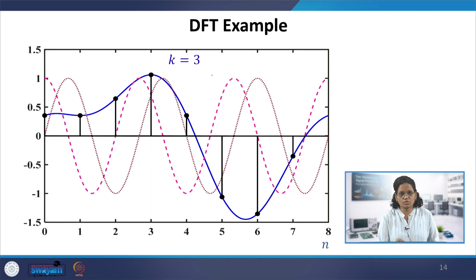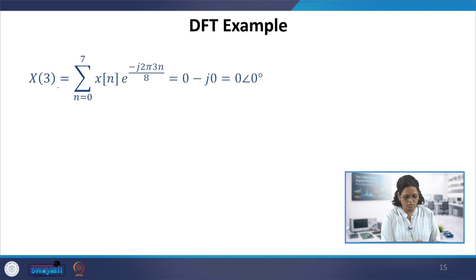In the case of k equal to 3, you can see that the sine wave and the cosine wave complete 3 cycles within the sample period, that is, within the n points we have taken. So again we correlate the sine and cos with the input signal, and we get the correlation coefficient as this value, which is the presence of harmonics. Now we'll see for k equal to 3; we have computed 1 and 2. K equal to 3 results in 0 because the input signal doesn't have the third harmonic. So that correlation would be 0. This is the absence of the third harmonic.